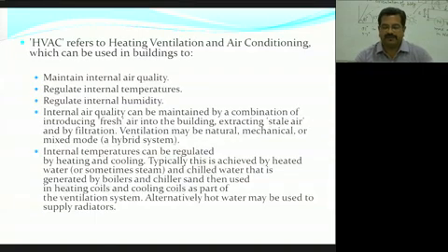Internal air quality can be maintained by a combination of introducing fresh air into the building and extracting stale air. It means the foul air has to be replaced with fresh air. And by filtration, if we have utilized filters in between, then by the filters we can have better air quality inside our building. Ventilation may be natural, mechanical or mixed mode, a hybrid system.